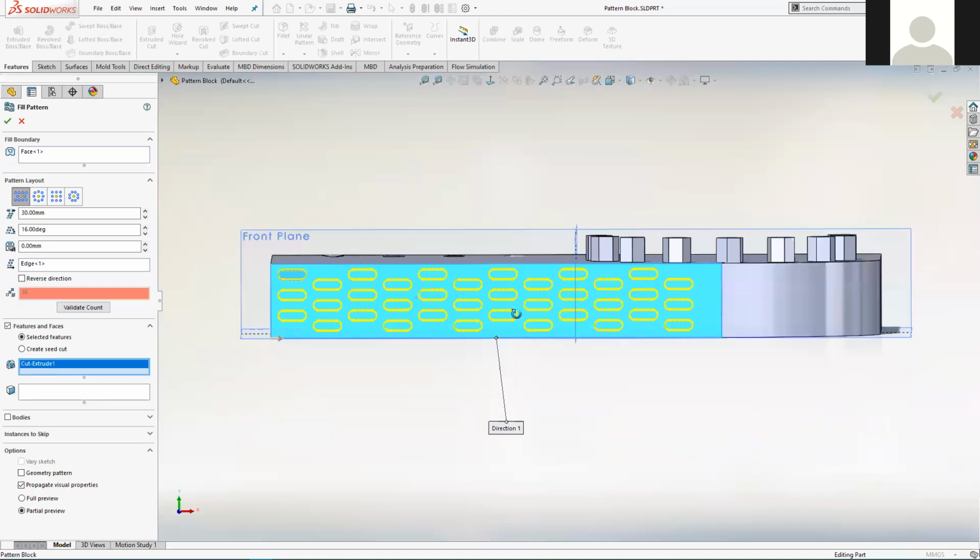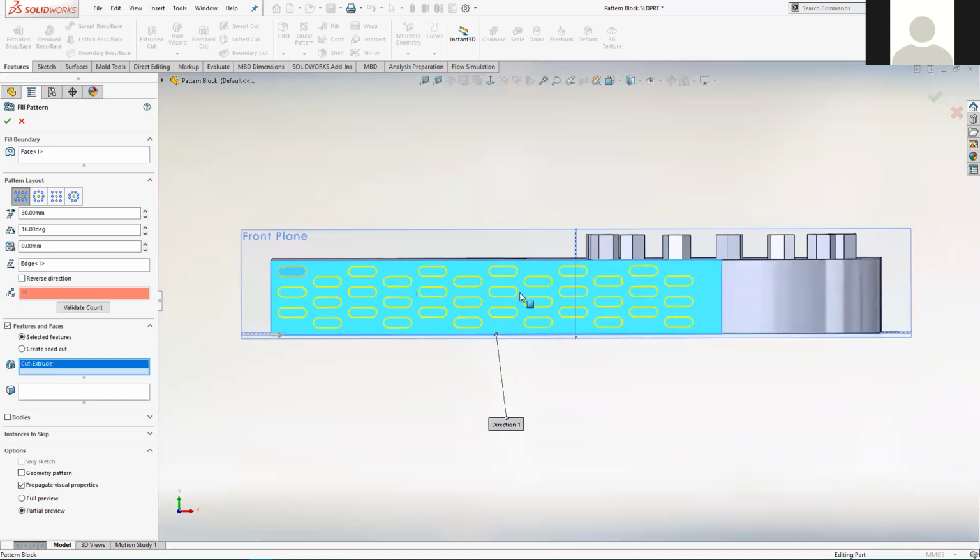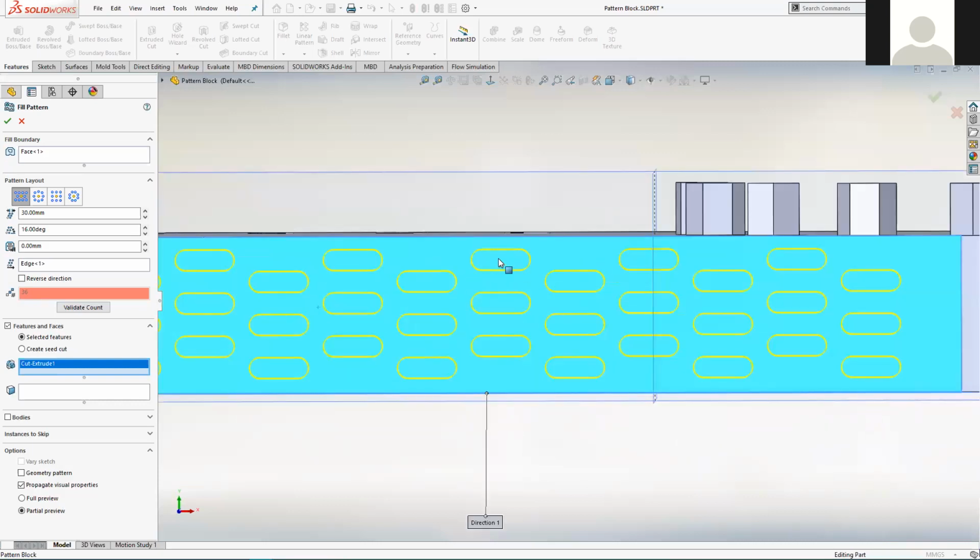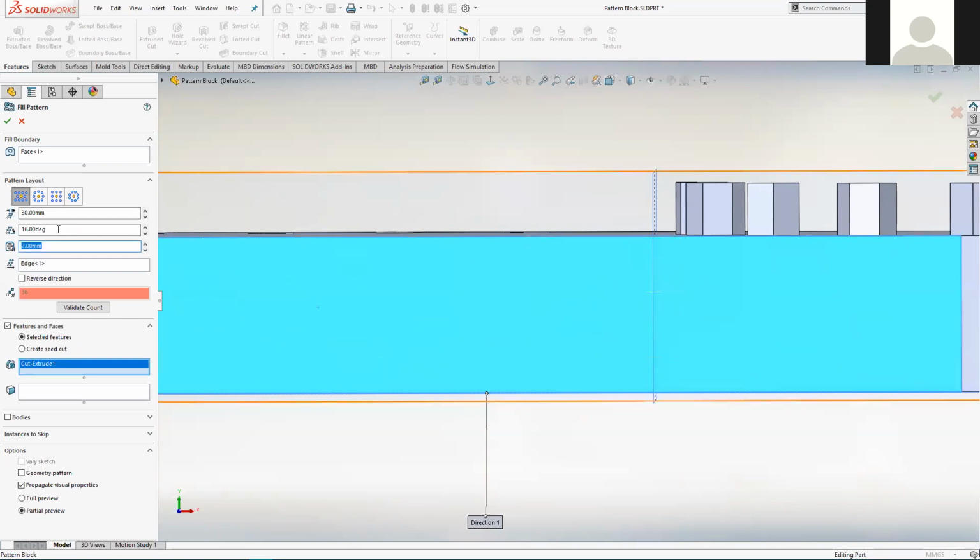So there's an option which tells the system to avoid putting copies too near the boundary of the edge. So if you're worried that, let's say, your thin metal sheet is getting too weak around the boundaries, you can put in a margin, just like you put in on a Word document. So it will tell it to avoid things which are too close to the margins.